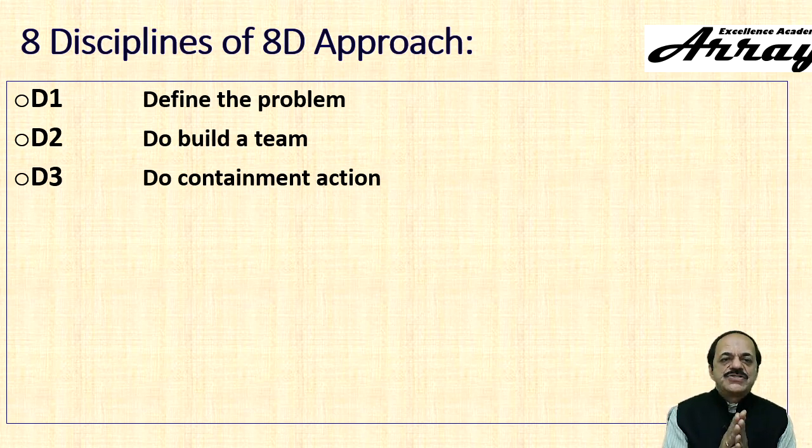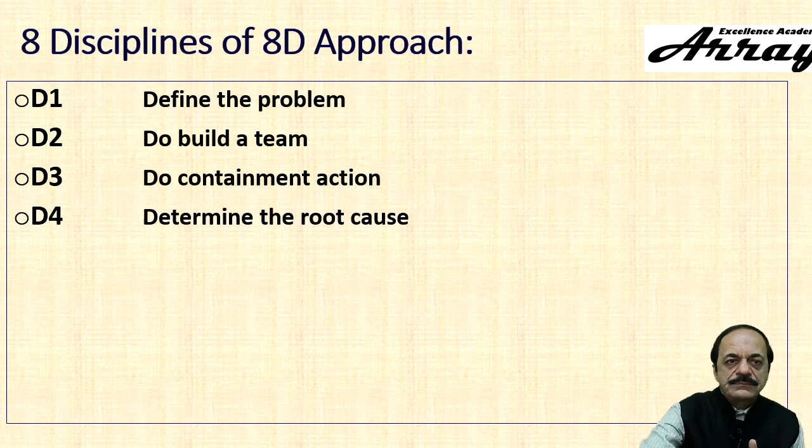Please remember, don't stop here. Look at the items in stores. Draw the items, do 100% inspection. If there is a problem, rectify and then only allow the items to be binned in the store. This is the containment or damage control action.